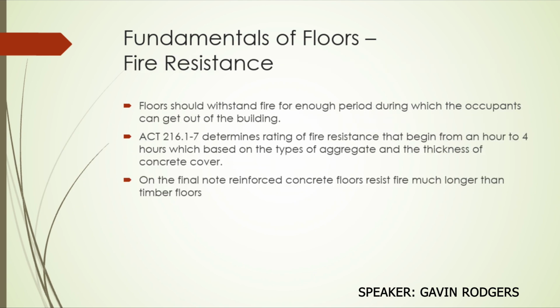Let's look at the fire resistance of floors. Floors should withstand fire for a long enough period during which occupants can get out of the building. The code that governs floors determines the rating of fire resistance, which begins from 1 hour to 4 hours, based on the types of aggregate and the thickness of concrete cover. On a final note, reinforced concrete floors should resist fire much longer than timber floors.